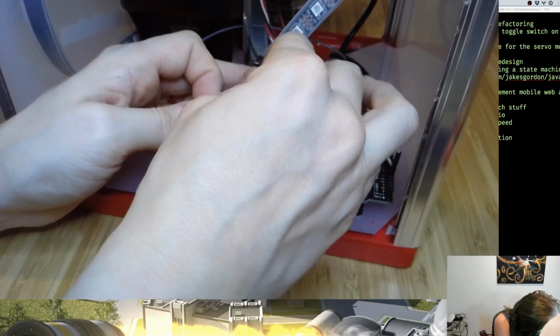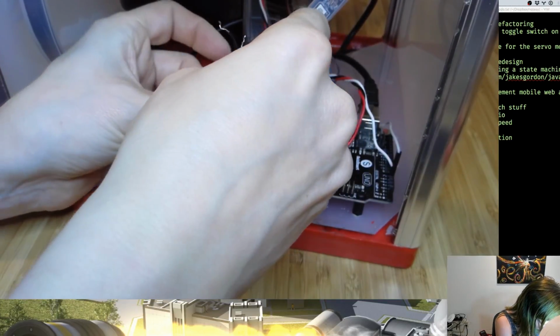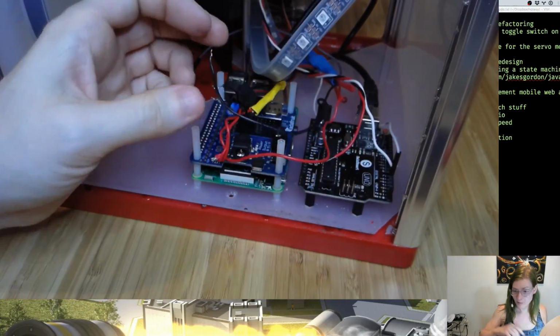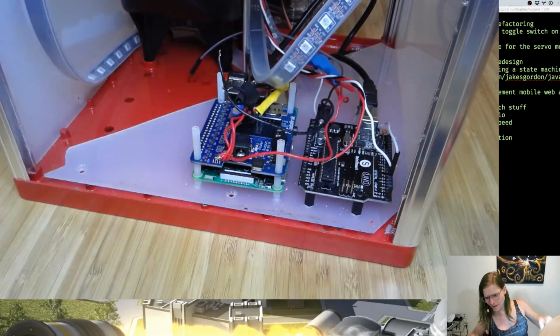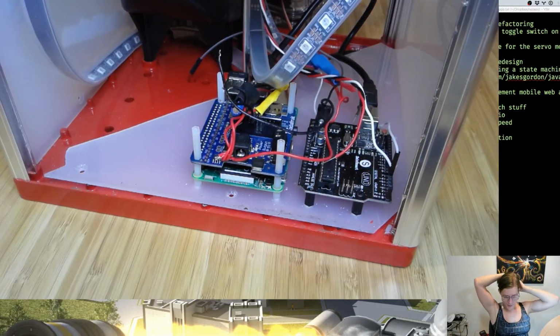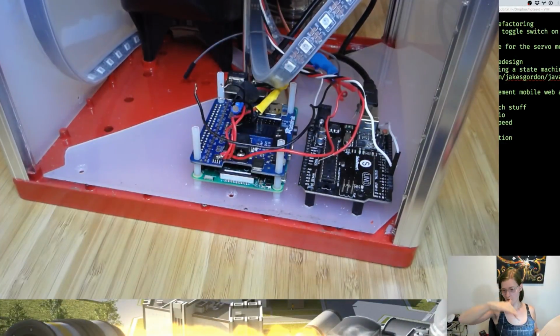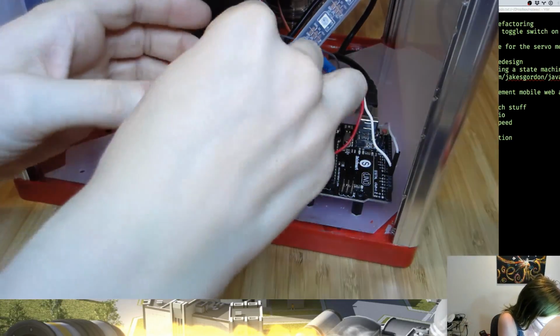This one goes off to the other side of the LED strip, because I'm driving power into both ends because it's a pretty long strip. It's like 190 little NeoPixels long. So you get less drop over the length of the strip if you just put power in both ends. And if you have a long enough one, you start putting power in in the middle.